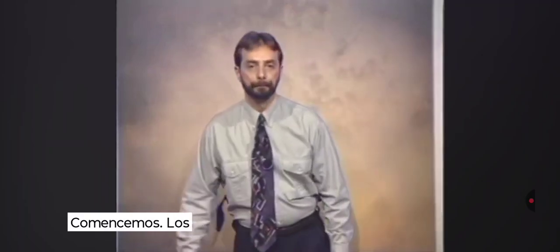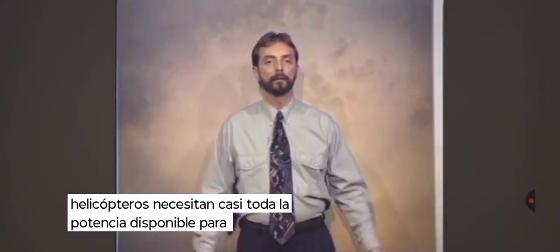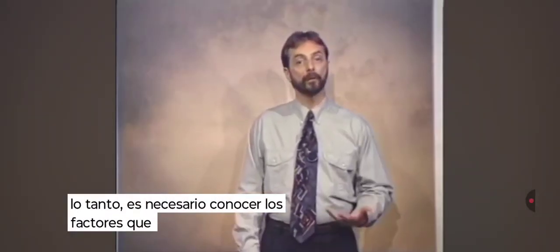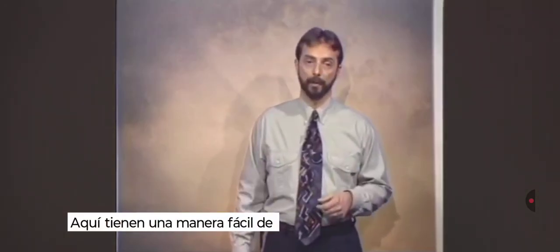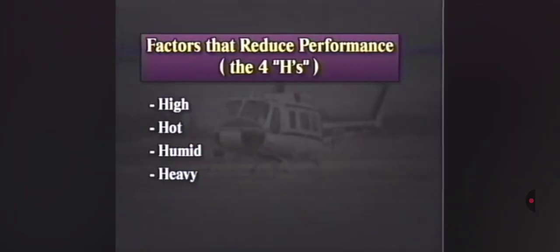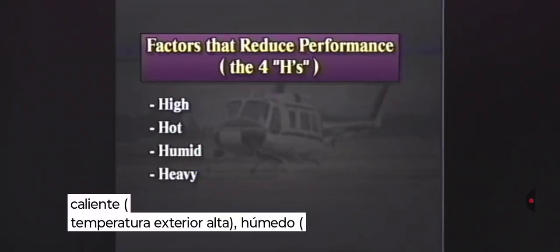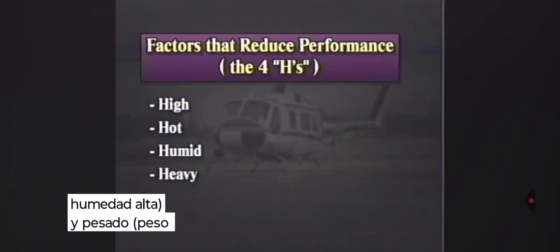Let's get started. Helicopters need almost every ounce of power available to fly. There's very little to spare. Therefore, you need to be aware of factors that can reduce the helicopter's performance. Here's an easy way to remember them, the 4 H's. High, meaning high altitude, hot, or high outside temperature, humid, high humidity, and heavy, or high gross weight.